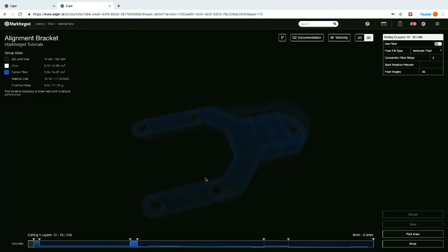That is something to keep in mind when you design for 3D printing and when you're laying your fibers. Fibers are always going to be, by the nature of a fiber, first off, stronger in tension, and second, stronger bending along the axis of a fiber rather than between layers of a fiber. This is something that can be solved whether in your print orientation or in your assembly, depending on how you're using the part.